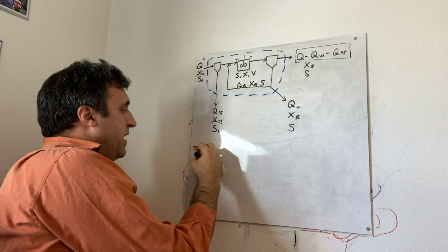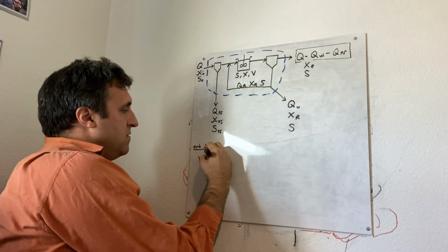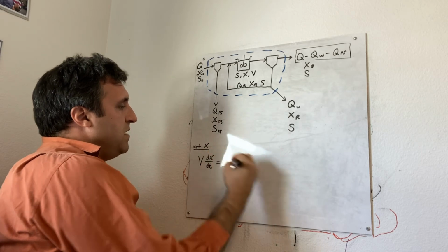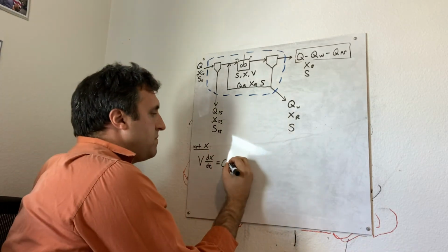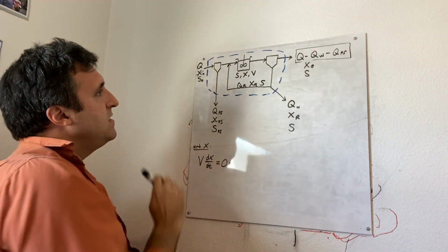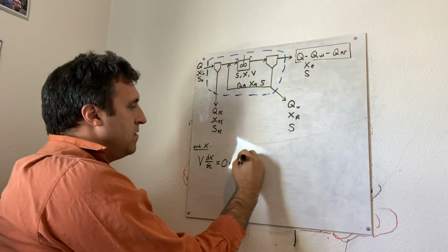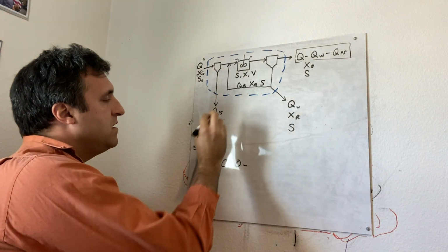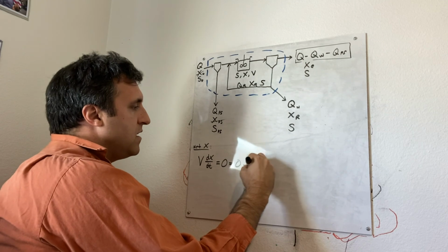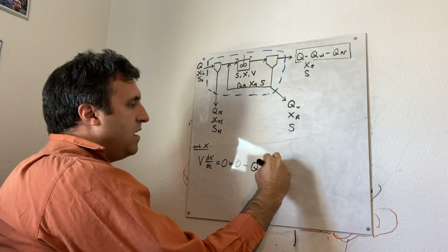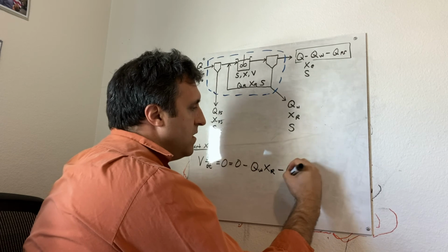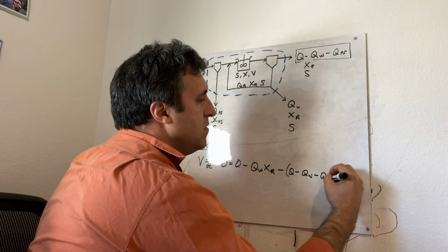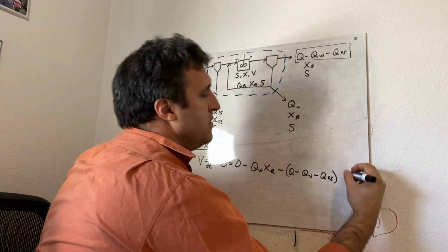So we want to take the rate of accumulation, which mathematically is V times dX over dt, and we assume that to be equal to 0 under steady state. And that's equal to what's coming into the system, in our case negligible, minus what's leaving the system. So this part we can consider negligible. However, we've still got the QW XR, and we've got (Q minus QW minus QPS) times XE.